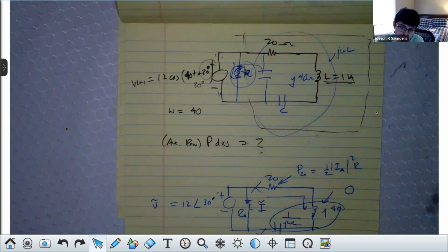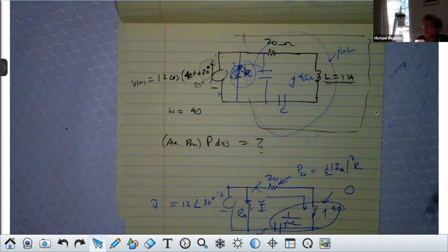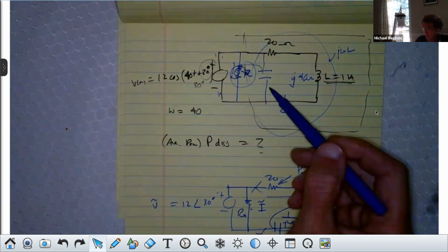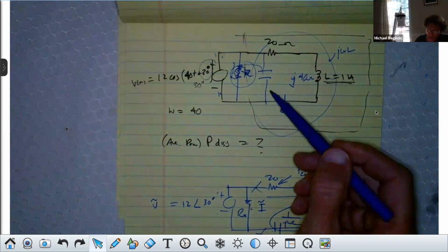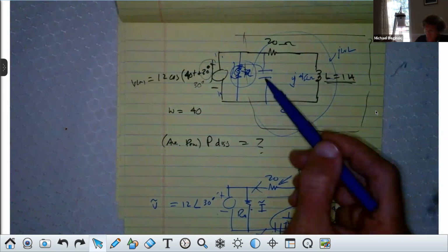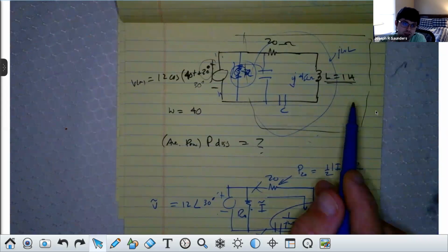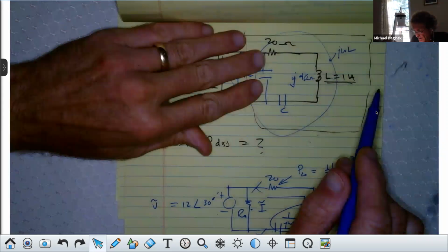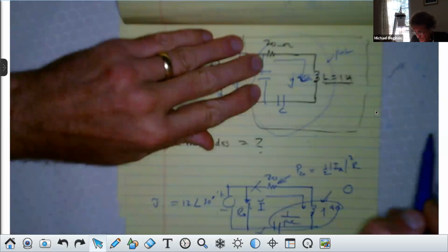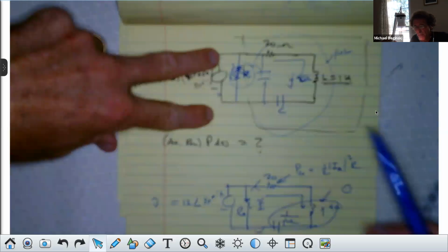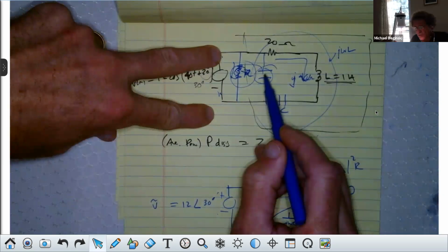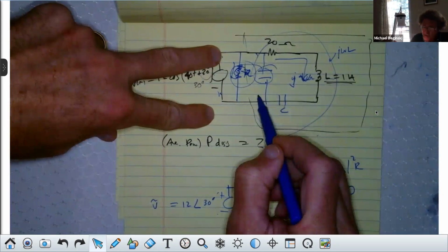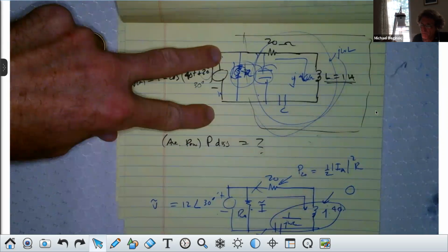Would it be the same thing as just adding the first resistor? No, a capacitor does not dissipate power, average power. That's my point. I mean, adding the first capacitor, adjusting the reactive element of the inductor. No, look, when I'm looking for this current here, this capacitor has no bearing on it because it's in parallel with the voltage, right? I can put anything in parallel with that voltage source and it has no bearing on what happens in that portion of the circuit. Nothing at all.